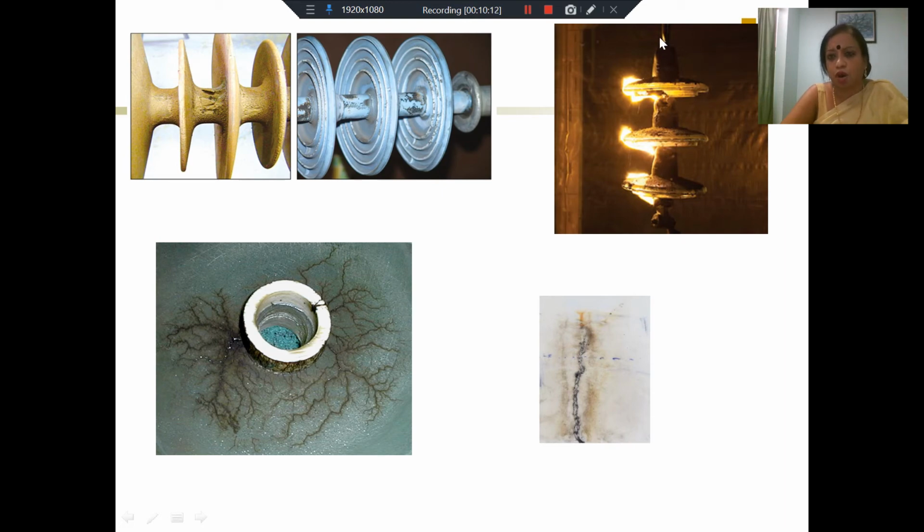The current is not actually breaching the entire electrode to electrode gap, but there are arcs being drawn along some of the total flashover path along this surface, and then traversing this, it should reach the low voltage electrode. Now this entire path is not conducting, but only sections of it are conducting, as you can see by the brightness of the current.